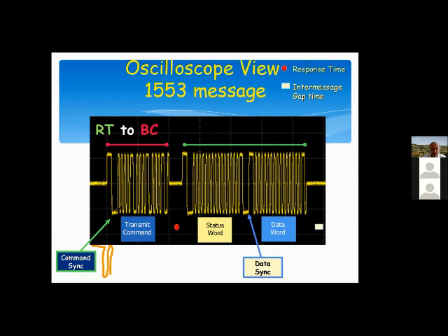The gap is this minus this. On the other hand, if I look at this signal, this is minus 3.75 and the other one is plus 3.75, the gap between them is going to be the reverse. So just by looking at the gaps, not relative to ground, just relative to themselves, I see, are these signals far apart or are they right next to each other? And that tells me, without reference to ground, whether I'm looking at a high signal or a low signal.